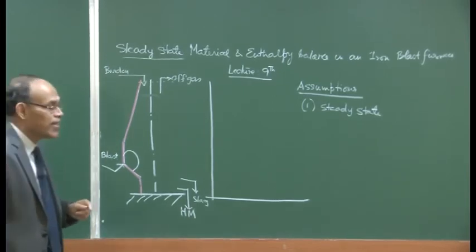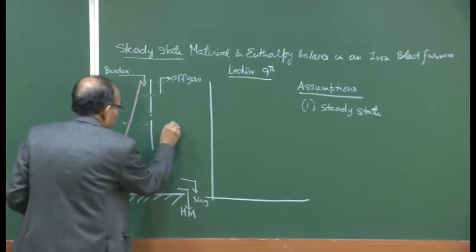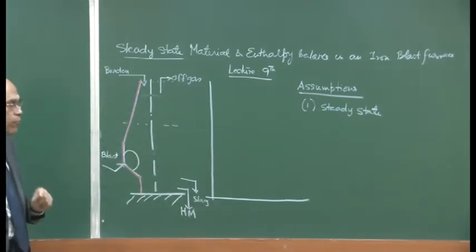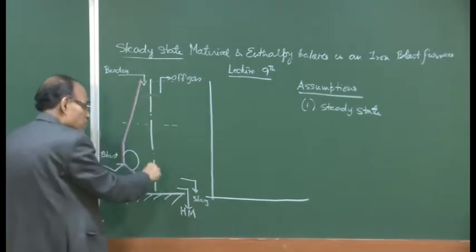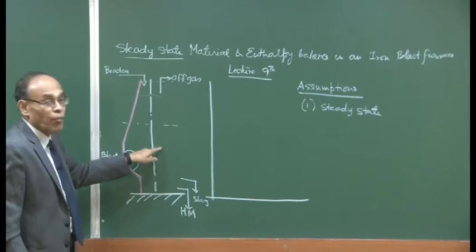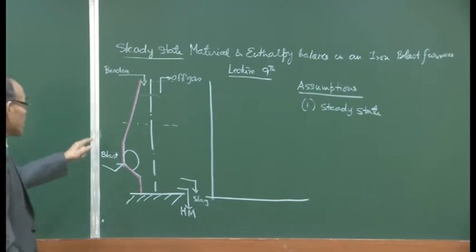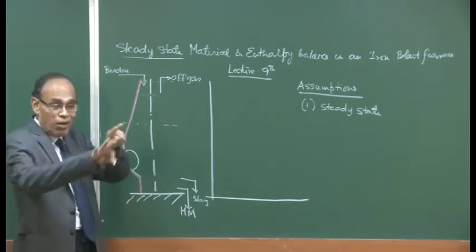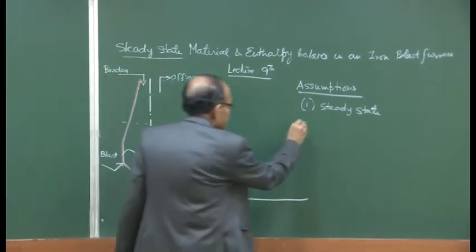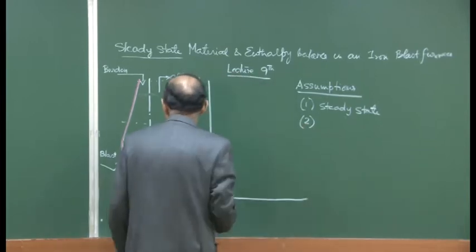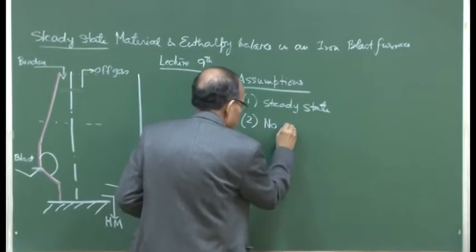What steady state essentially indicates, one implication, is that I can bifurcate the blast furnace at any point. I can segmentize it. The only thing I have to consider is that the material which is leaving the upper part is the same material which is entering the bottom part. So the continuity of flow of heat and material must be respected across this artificial partition of the blast furnace itself. We will make an assumption based on our knowledge that there is no oxygen present in the metal.